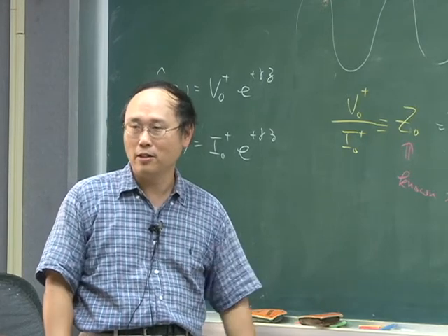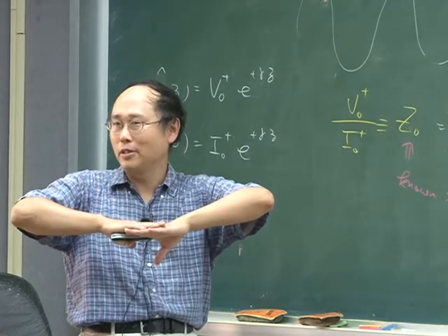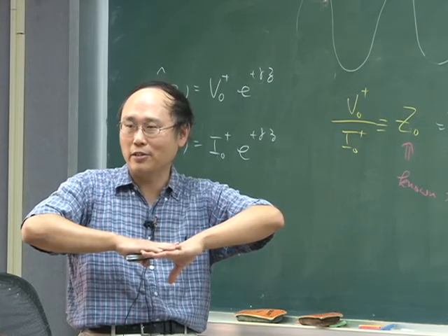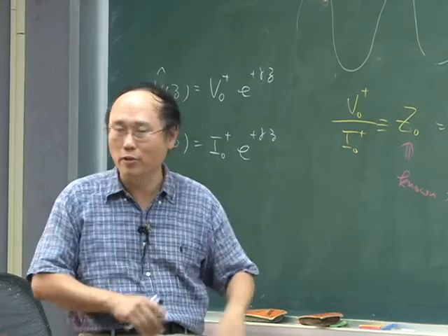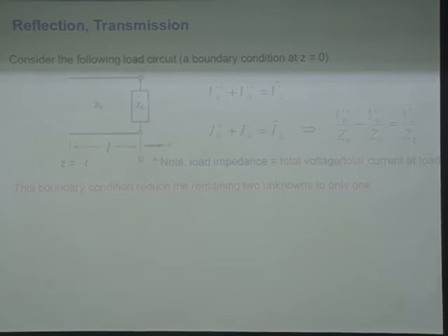You only get interference when two waves are superimposed on each other. For a transmission line, the interference comes from the reflection of the wave. Think about this: if you put some load at the end of the transmission line, this could be an antenna, for example. Then when the wave is incident on this location, there could be some reflection back.